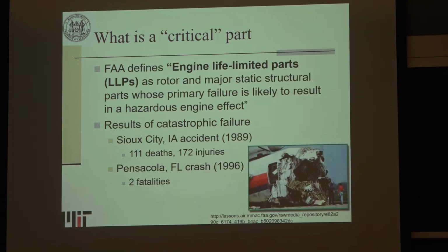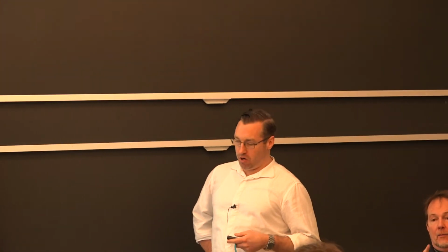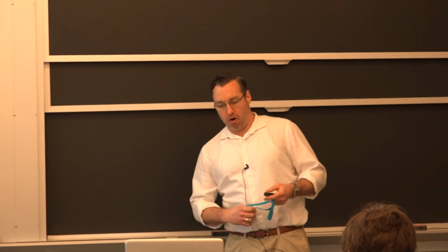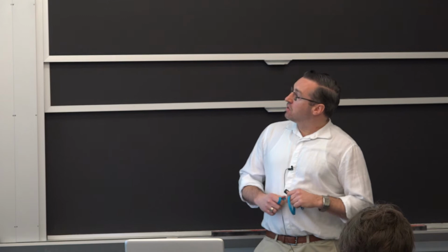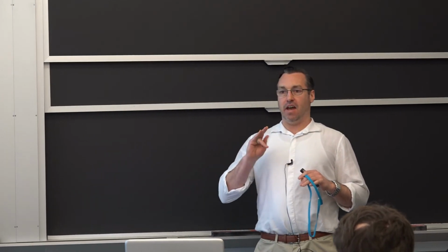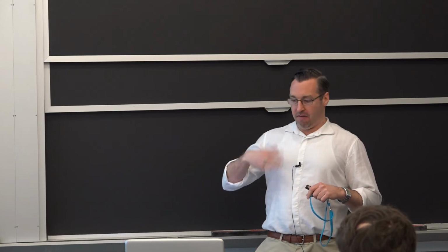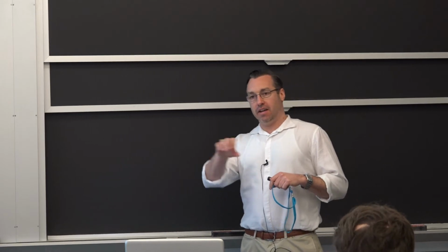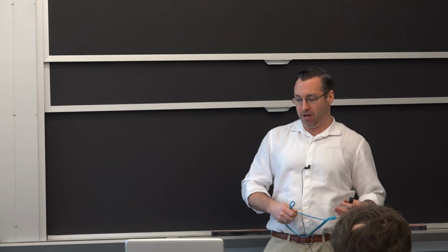So what is a critical part? The FAA, Federal Aviation Administration, defines engine life limited parts, LLPs, as rotor and major static structural parts whose failure is likely to result in a hazardous engine effect. A hazardous engine effect means an uncontained engine, which means that some part, whether it be a disc, a blade, or vane, or another engine part, can actually pass through and be released from the engine in operation.